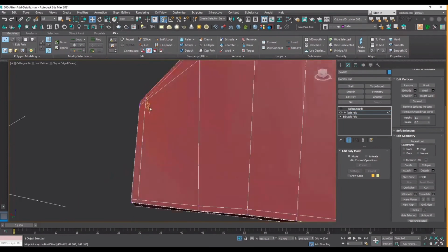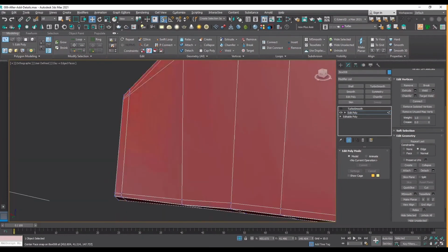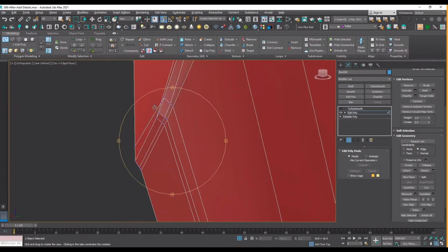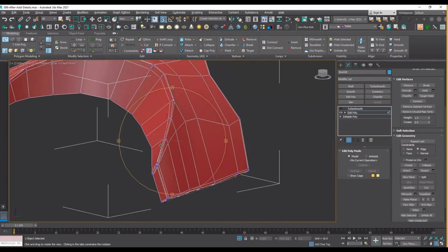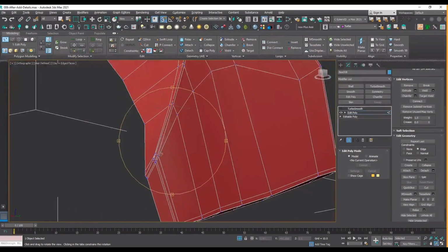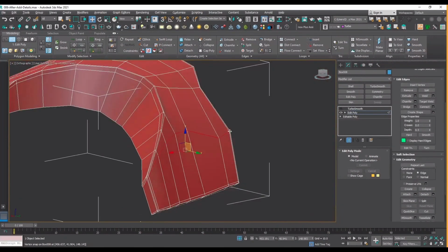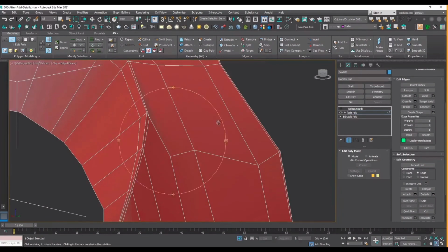Next step, as before, is to prevent these close vertices and edges. But instead of deleting, which results in our model's deformation, we can redirect the edge loops and put the vertices in the right position, and also delete the unnecessary part. So I deselect and just Control Remove.